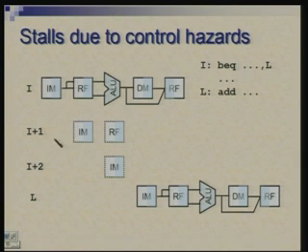I'll wake up only when I know, but meanwhile let it continue with the instruction in sequence. So the hardware will pick up the next instruction because PC plus 4 is already there, start it, in the next cycle take I plus 2 instruction and push that in the pipeline, and here you realize that probably you have gone wrong, and then you abandon this, flush it out of the pipeline and start something which was actually required. Okay. So here you are doing something in anticipation.